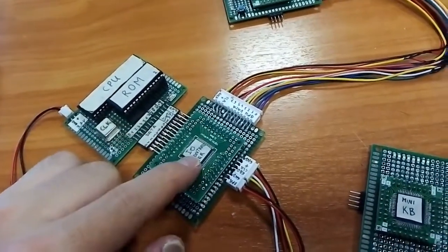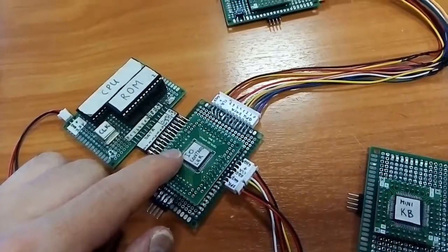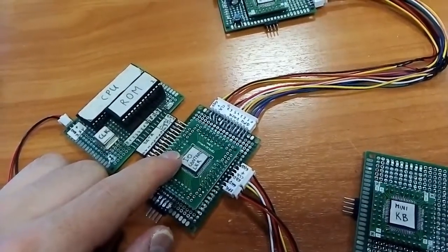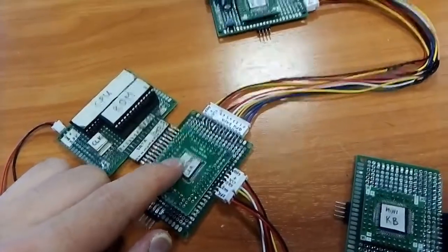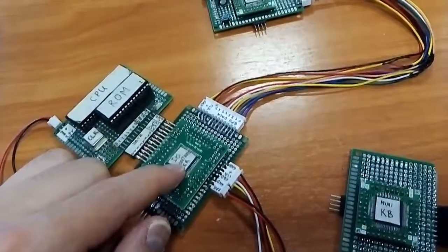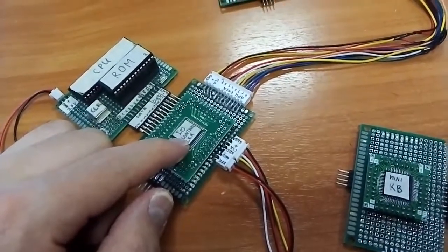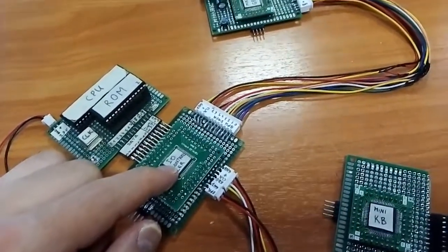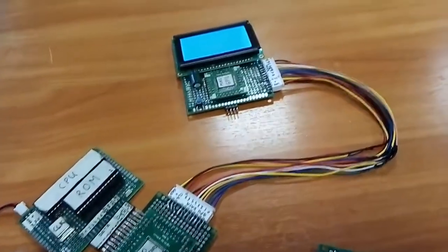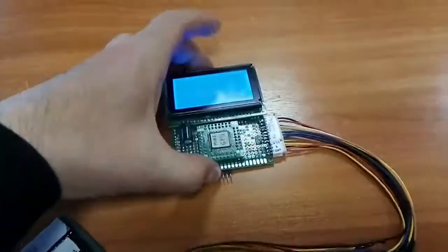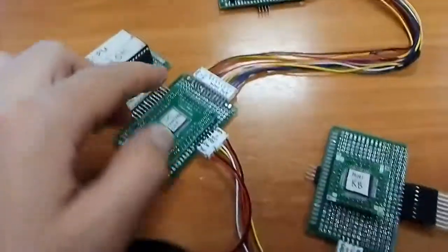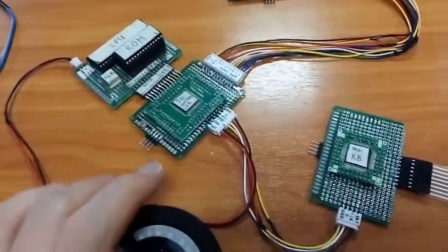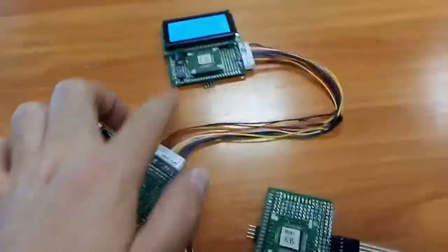And this one, as soon as he has received all the required data and the marker end of data AA, holds this data. He's been collecting it into his memory, and now he's going to read it and analyze it, byte by byte. For every byte he watches what type of byte it is by looking at a specific bit. It determines if this is the byte for him or this is the byte for him, and it sends to them their parts.